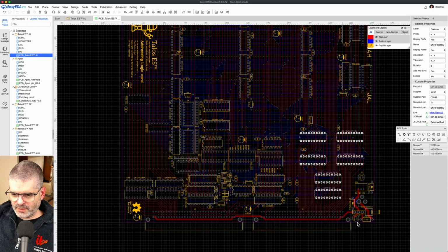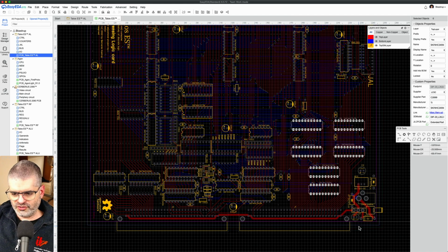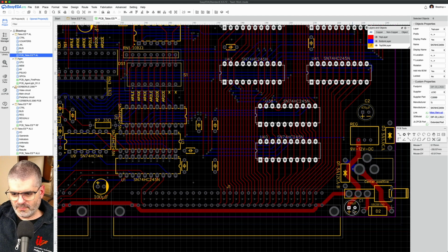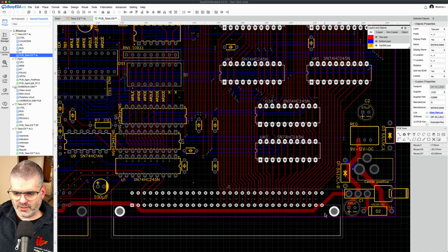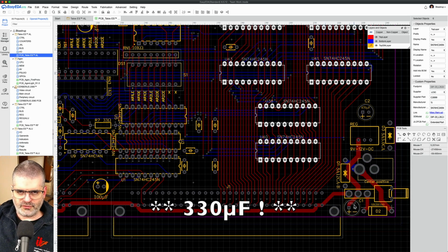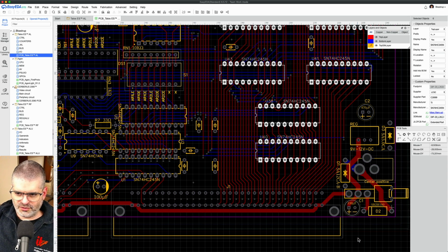That's the power supply part, which is in here. C1, the capacitor that, if you've made the previous cards, you should change, is this one here. It's right next to the power switch, and right next to one of the backplane connectors. This is the one that is now 33 microfarad at 16 volts instead of 470 microfarad at 6.3 volts. This is a 12 volt line, so that will not work.